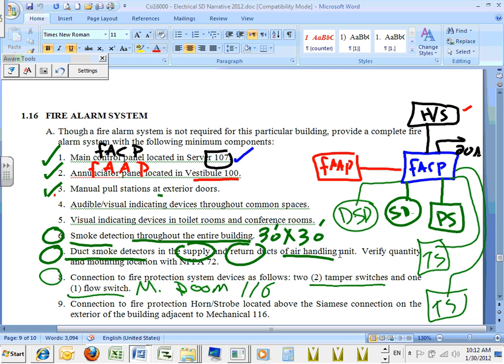Two feeds coming to the building, two branches. Sometimes you have a big valve coming in and you split your building into different pipes, one pipe going to system 1, system 2. We're assuming here we have two systems, two valves, so we need to control the two valves. Two systems, two sprinkler systems.